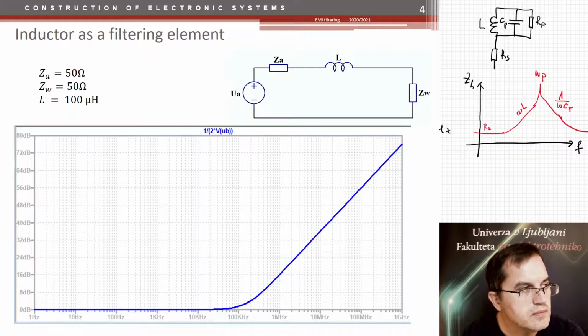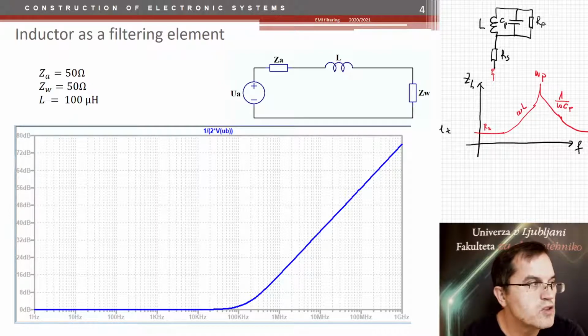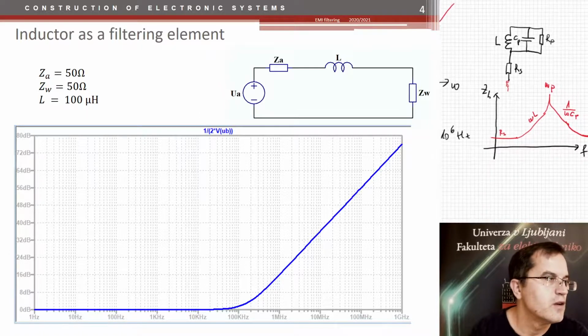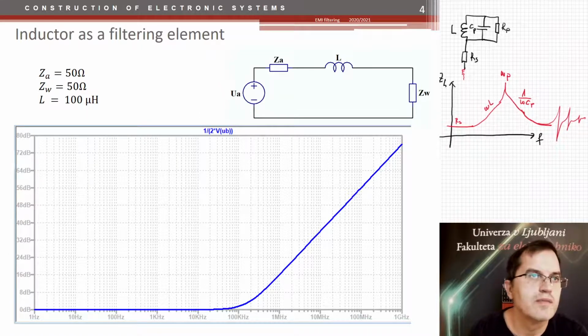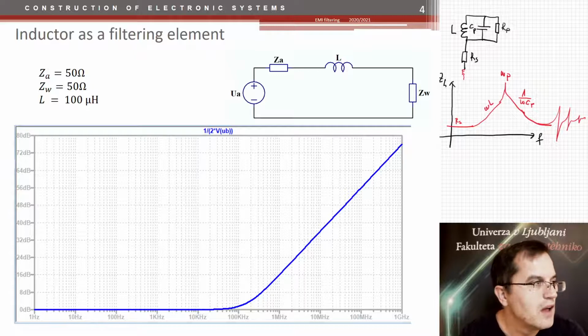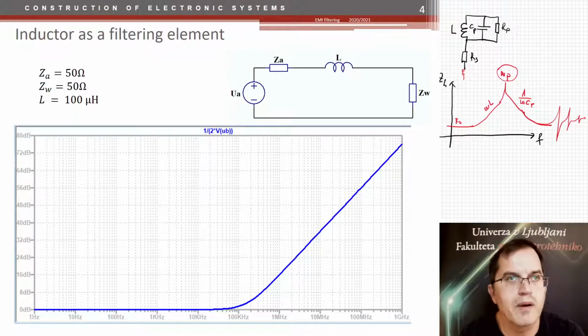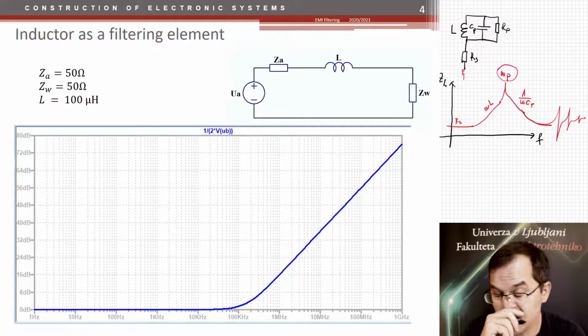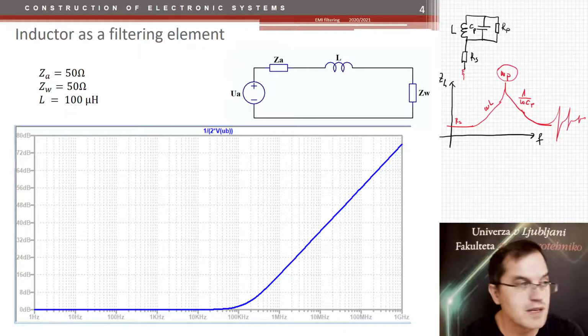Now there could be some series inductance as well, which is the inductance of wires, which has almost no parallel capacitance. So we'll have some sort of a secondary effect after that, which is actually shown here. Now, this is the main part, the main frequency, omega parallel, which will tell you at which frequency the coil becomes a capacitor.